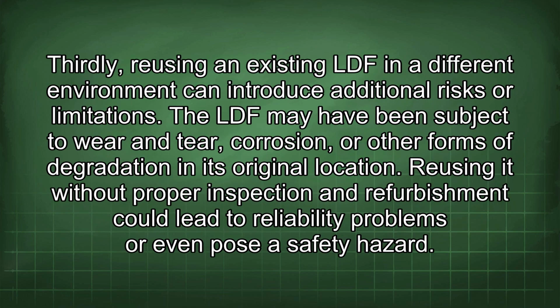Thirdly, reusing an existing LDF in a different environment can introduce additional risks or limitations. The LDF may have been subject to wear and tear, corrosion, or other forms of degradation in its original location. Reusing it without proper inspection and refurbishment could lead to reliability problems or even pose a safety hazard.